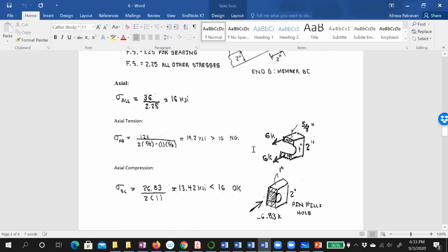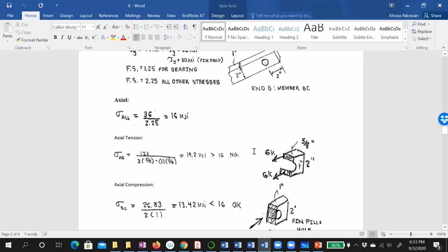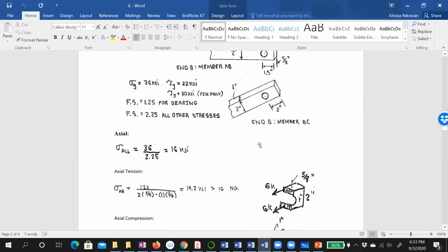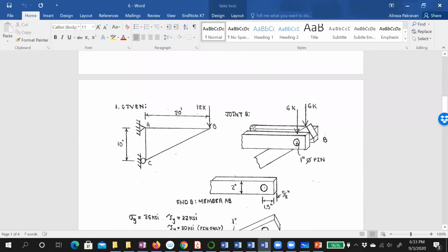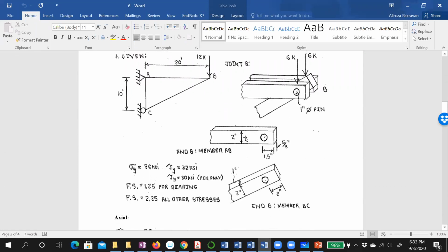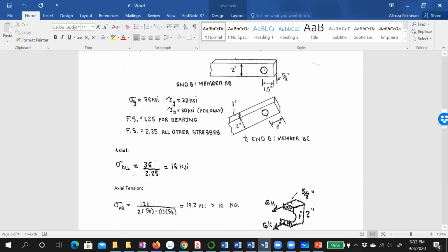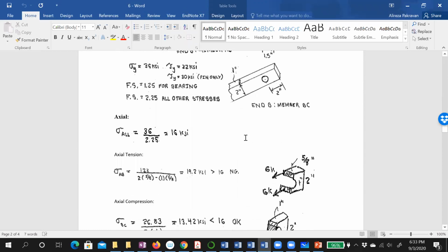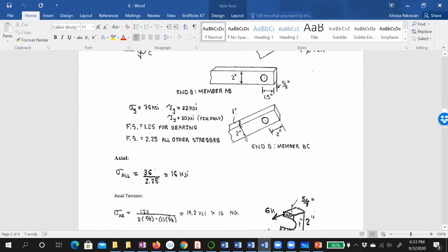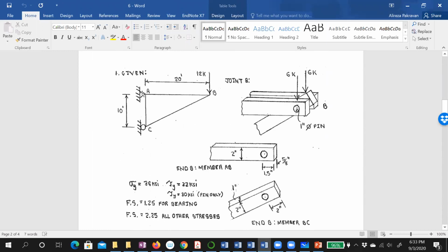Kind of. I don't know if I'm just getting confused. What exactly is your question? Force AB is 24, and then we're only using 12. Is that because we divided by half, or is it just a coincidence? Yes, FAB is 24, and the force we're using is actually half. Yes, because element AB has 2 beams parallel to each other.